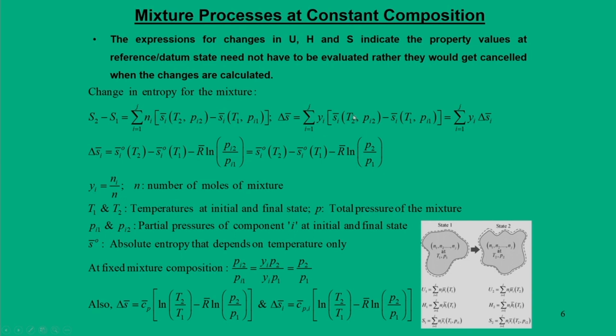Now the important aspect we need to calculate is this delta S i, for component i, the molar specific entropy change. By the definition of entropy calculation earlier, this has to be calculated with the concept of absolute entropy. When you deal with absolute entropy, the choice of pressure is meaningless.